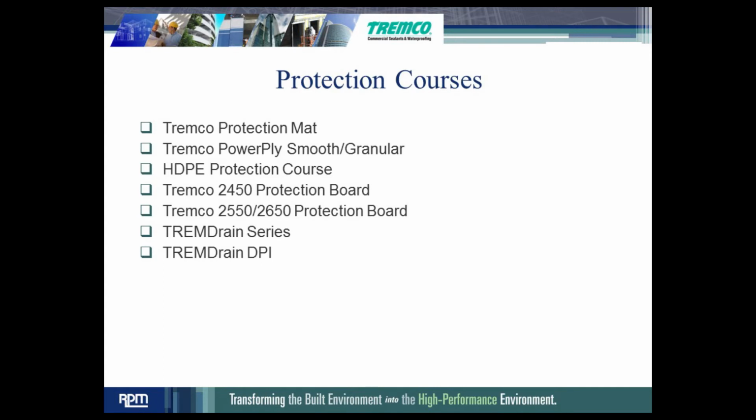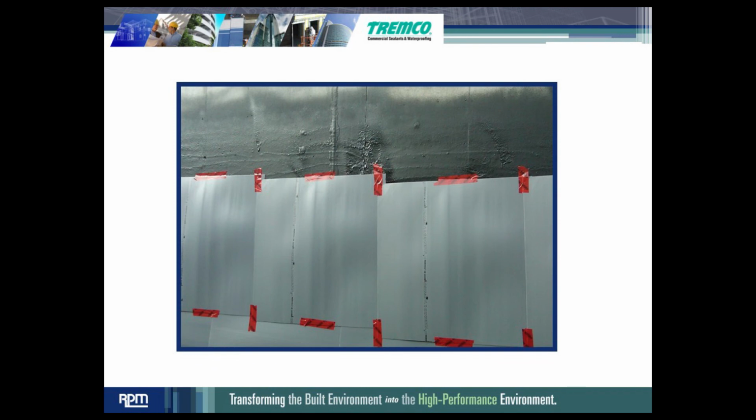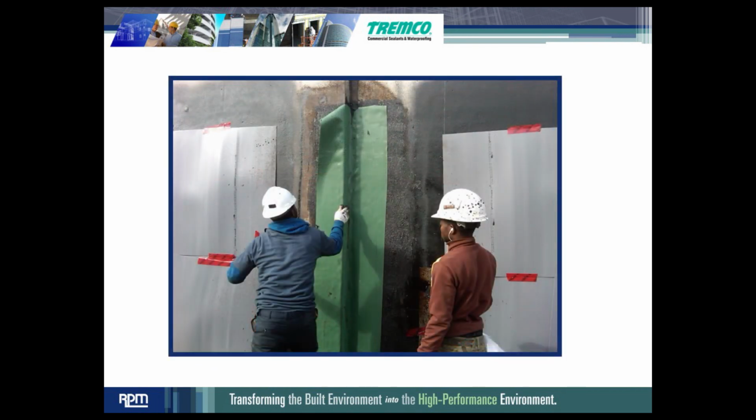We have many different options for protection courses, but down here, I don't remember the one that you have. Unfortunately, you only have one of the options for the protection courses down here, and I don't recall which one that was, but you can see the protection course coming in over the membrane. So when they backfill onto that, the membrane is protected.